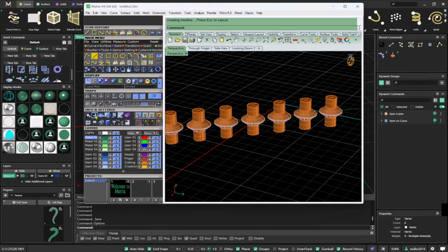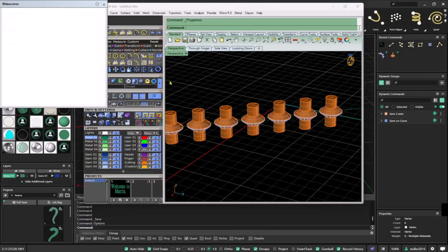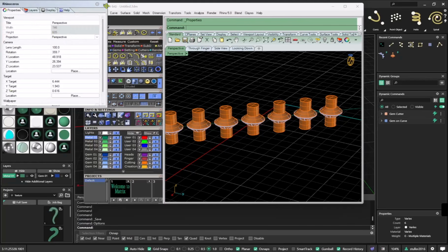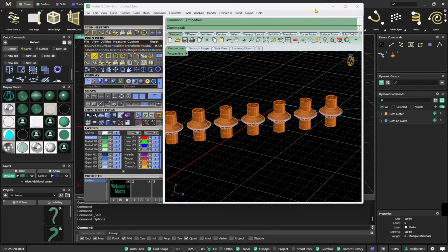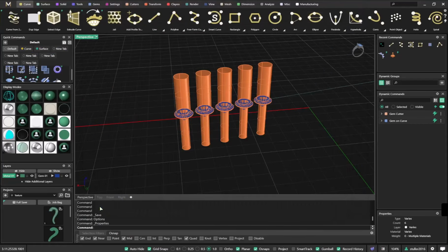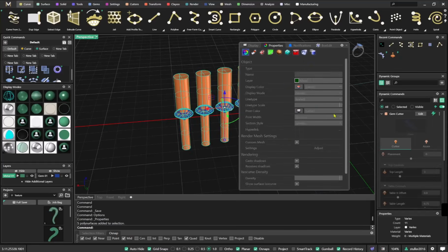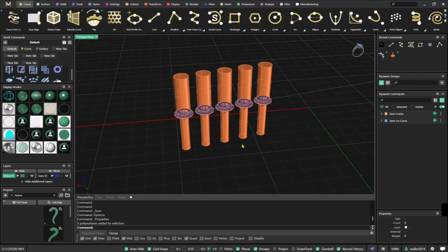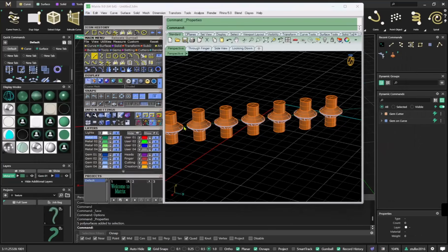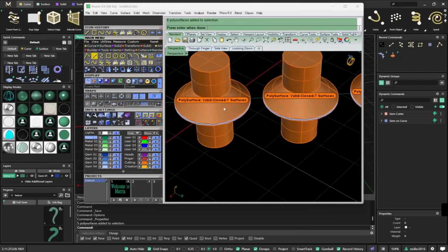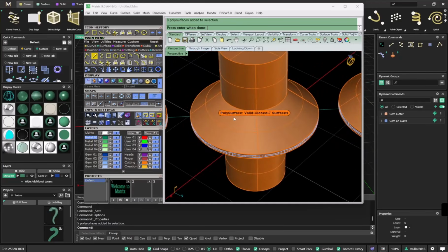We have a properties panel or object properties. Just by clicking, you have it here. In MatrixGold, we dedicated Control T. So if you press Control T, we have the properties panel, and if you select an object, it shows the properties of the object. Normally I close it because I don't want to occupy my screen. And here we have object info. If I click on that one, it shows you the features of the object, which we call object info.